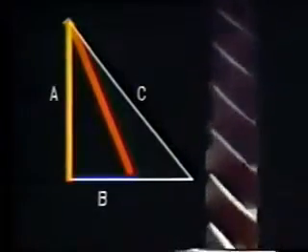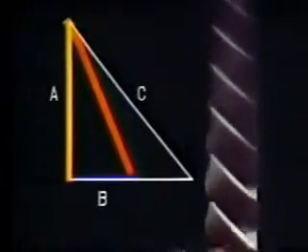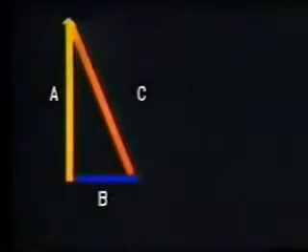But while the forward stages are pushing air, the rear stages aren't able to move it on rapidly. Here's the result. Vector A is now the direction and speed of the rotor blade. But the airflow has slowed down due to blockage in the rear stages. Here's vector B again, with its velocity component shorter than before, representing a drop in airflow speed. Here's the resulting relative speed and direction of airflow on the blades.